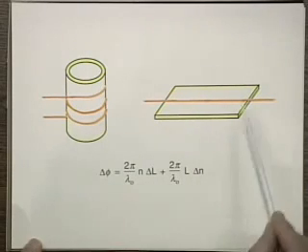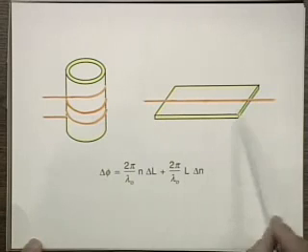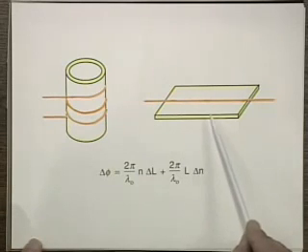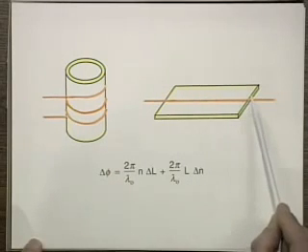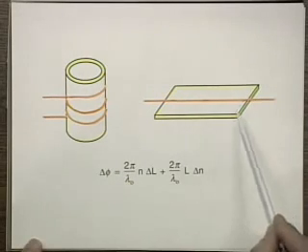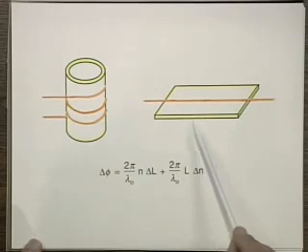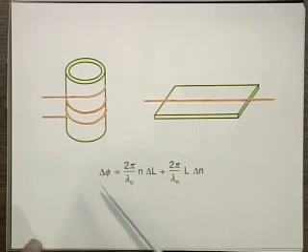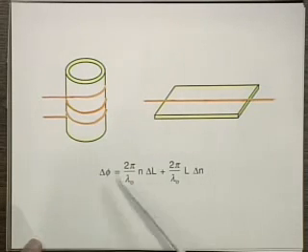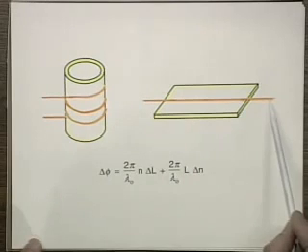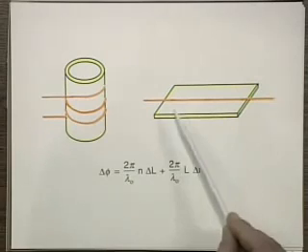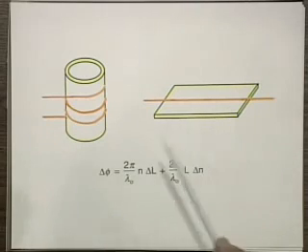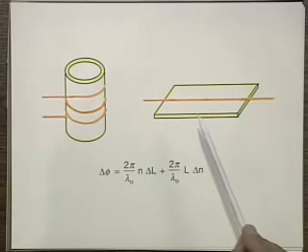Another type of piezoelectric device is a sheet. It is a piezoelectric strip or sheet where the fiber is just attached, bonded to this. You don't have to bond it that rigidly to this sheet. And then by applying a voltage between the upper and the lower surface, you can again stretch the fiber, and then you can essentially modulate the light that's propagating. So that's a very neat way. You don't have to break the fiber; it's still intact, and you can get phase modulation.